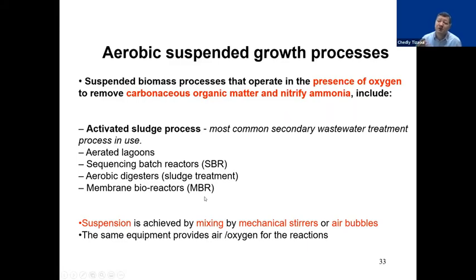They are more or less the same as an activated sludge process, but the only difference between the two is the way you make the separation between the sludge you form, the solids you form, which represent the microorganisms and bacteria that are formed in the reactor. In the traditional activated sludge, they use simple sedimentation. In the membrane bioreactor, you use membranes to do that separation.